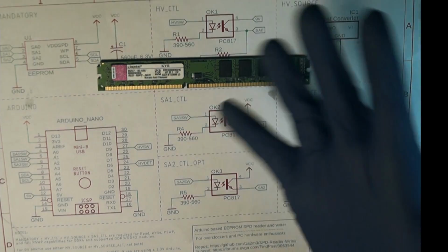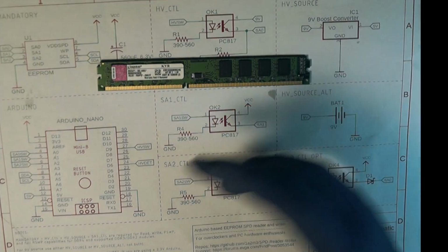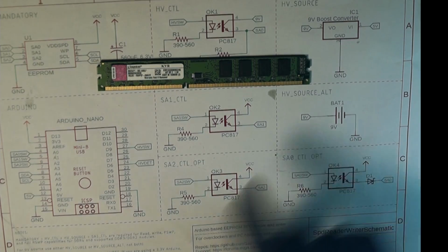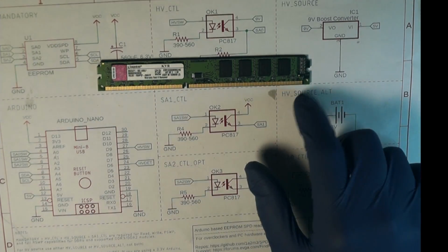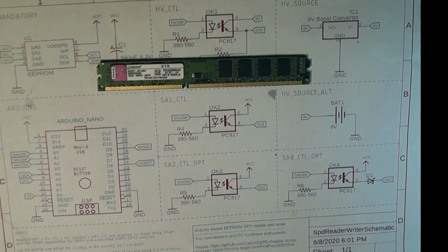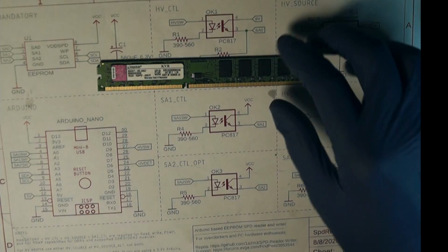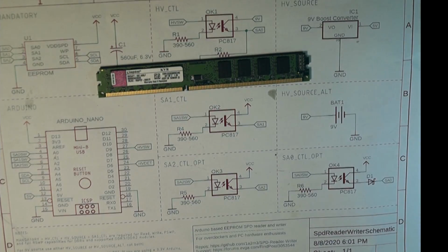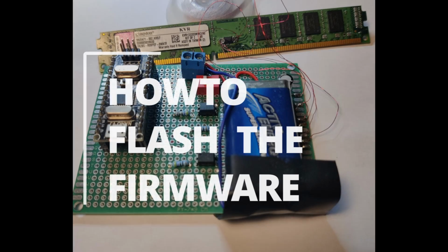The upside for soldering to the PCB is you can remove it and then you won't see it. It's pretty clean compared to having solder residue on the pads here. But it's an optical problem. If you have it in the socket, you won't see it. It won't interfere with the operation of the DIMM at all. So if you're happy with having messed up pads, whatever, do it. No worries.